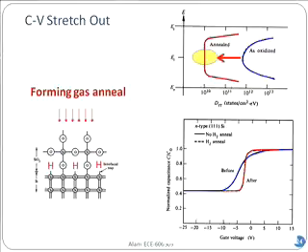The flat band is close to 1 and the threshold voltage has gone down significantly. Do you see that? It's about -2, -3 volts. This has happened because all the interface traps that were trapping charges before, this QF and QIT, that was the interface charge, have been taken out. Therefore, your threshold voltage has gone back.